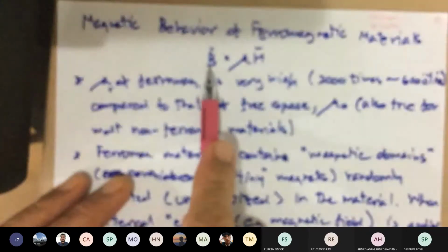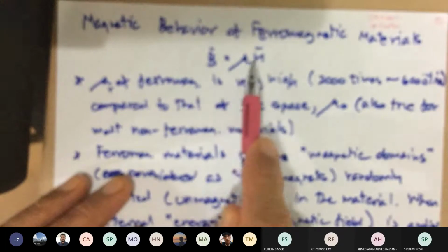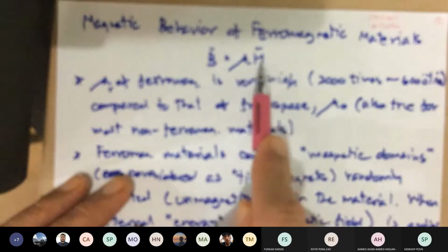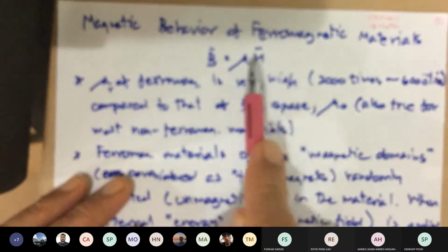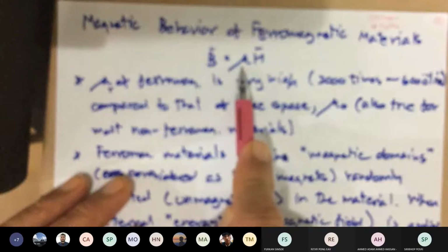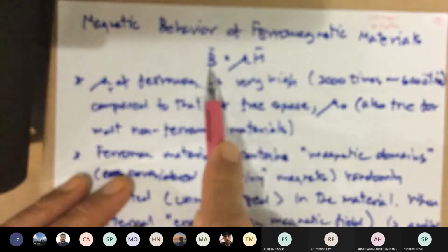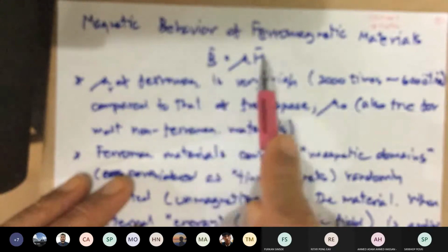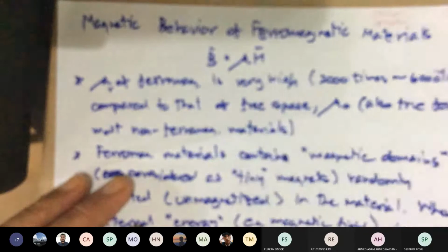And we found this equation earlier that your magnetic field or flux density B depends on this mu, which is the property of the core material, and the effort of producing that, H. Remember, same effort, but different property of material, you get a different B. We like B, we don't care about H, okay?